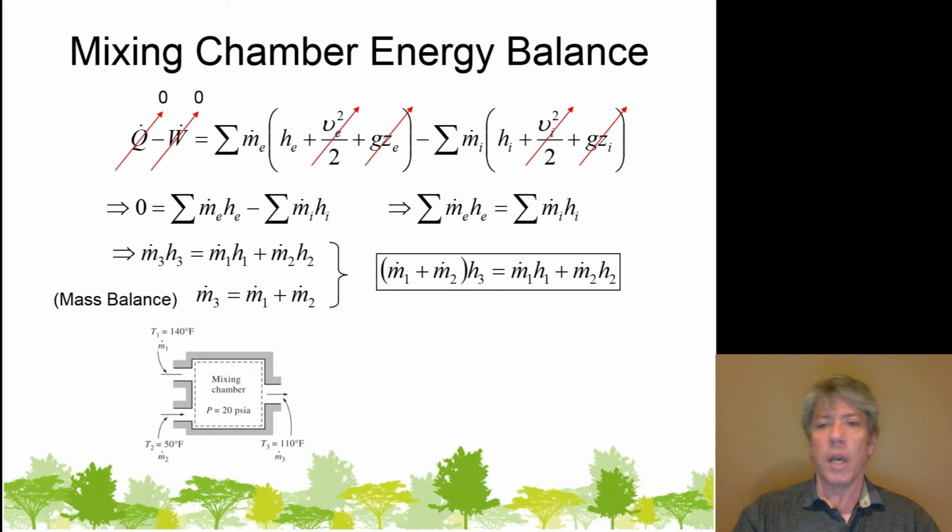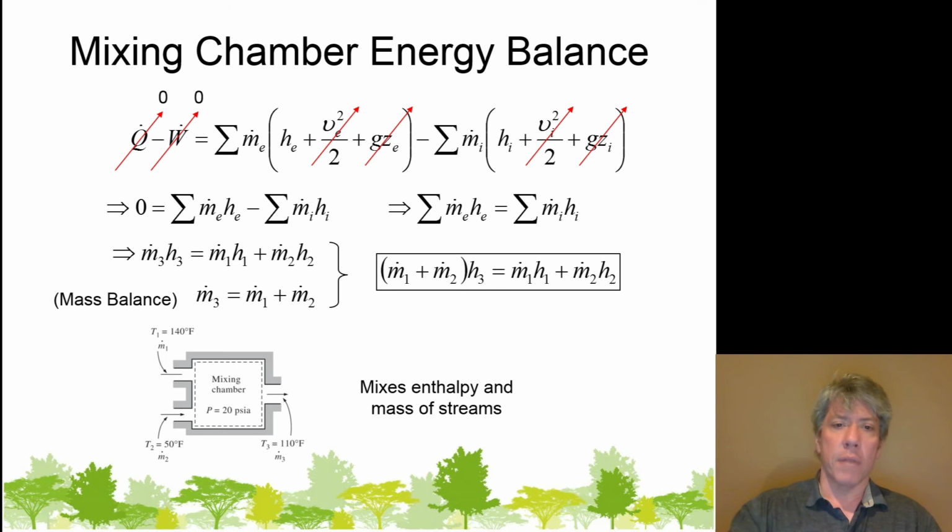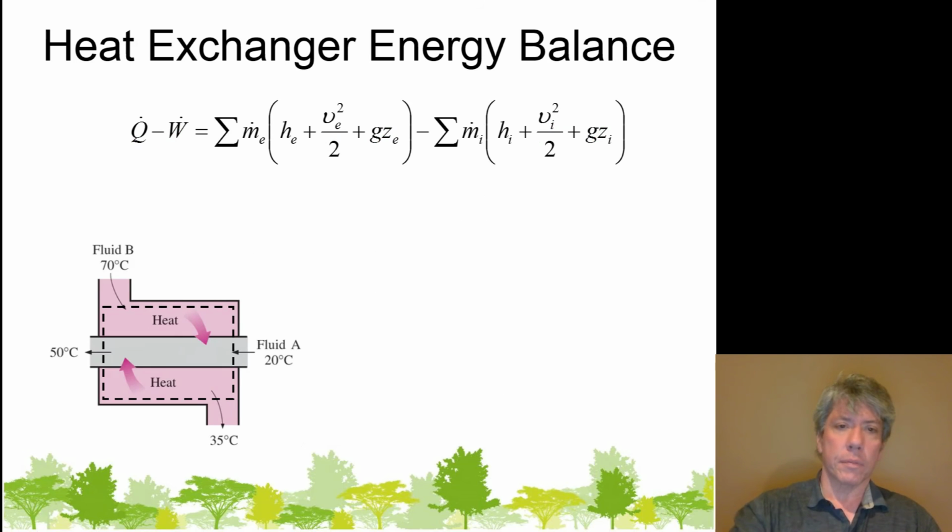You probably should. But what we really need for a typical mixing chamber is this equation. All that a mixing chamber really does is mix the enthalpy of incoming streams. It mixes the energy together and puts it back out. How about heat exchangers? Well, if we perform the same analysis, we can argue very similarly to how we did